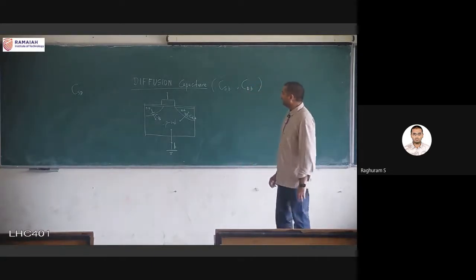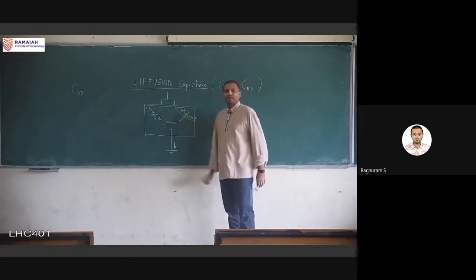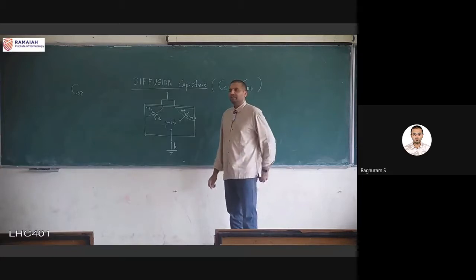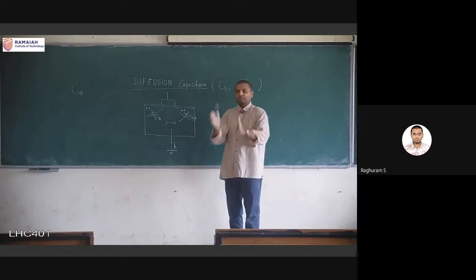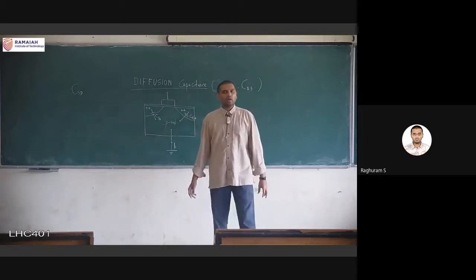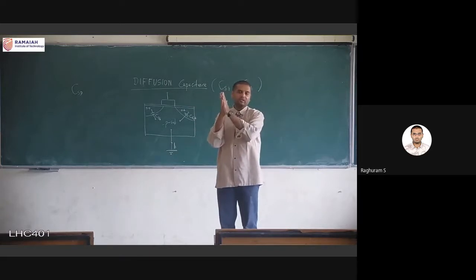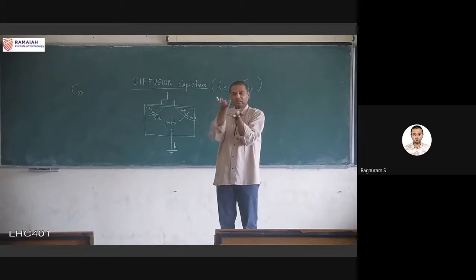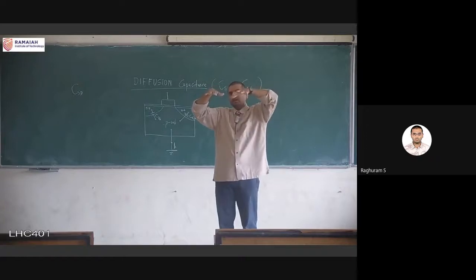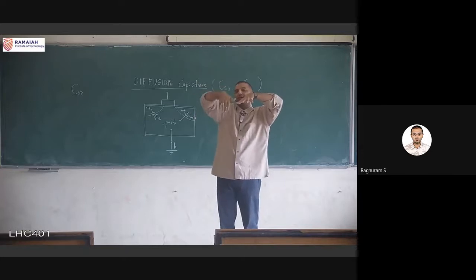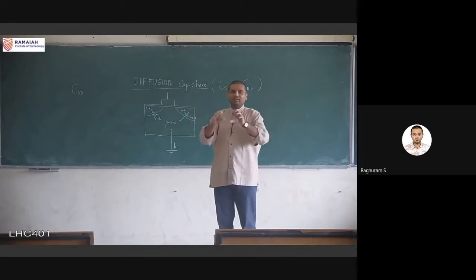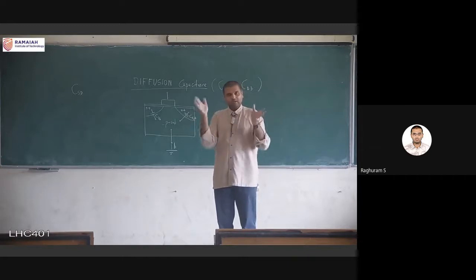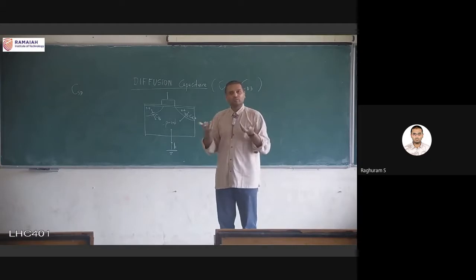The reason it is connected to ground, so that even though this doesn't look anything like our PN junction, if you remember from linear integrated circuits, you might have learnt about the PN junction. Anytime you have a P-type material and an N-type material joined together. This is interesting. PN junctions are not formed by joining P and N together with Fevicol or with sellotape. We have a silicon substrate. In one part of the substrate, the doping is with P, during which the other part is covered. Then you cover the part that has been doped with P-type and do N-type doping. So in the same substrate, you have a PN junction. It's not that somebody makes P, somebody makes N, and they bring it together in their car and join them to make a PN junction. It is from the same substrate, just with the control of doping using our mask and photolithography, that we make this PN junction.